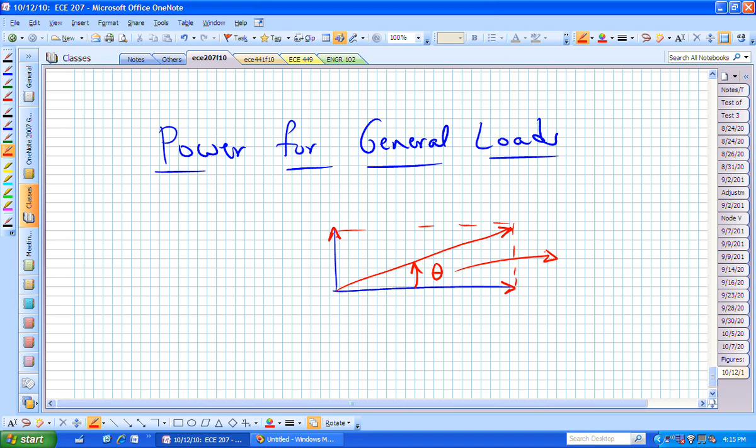If the power factor of a big industrial plant gets below 0.8, there may be a surcharge that you have to pay. And they're going to say, oh, your power factor was 0.75. You have to now pay a tax, basically, on the use of the power because this vector is longer than this guy.